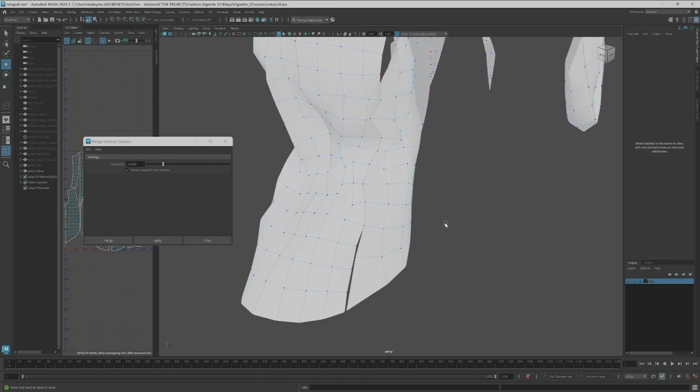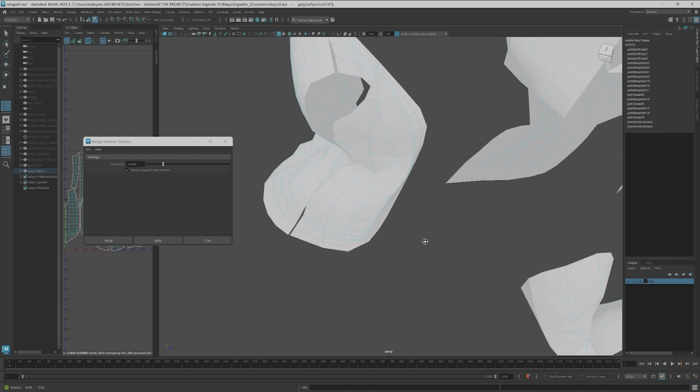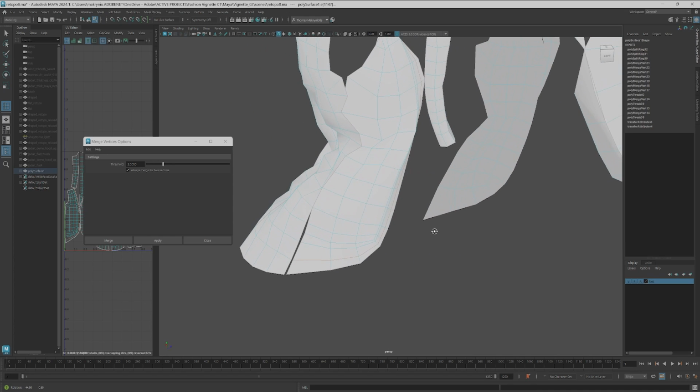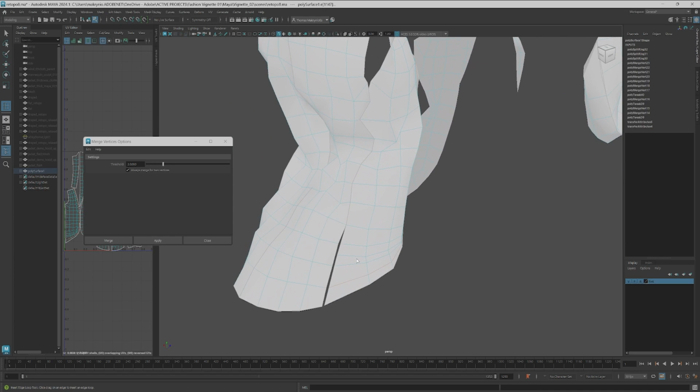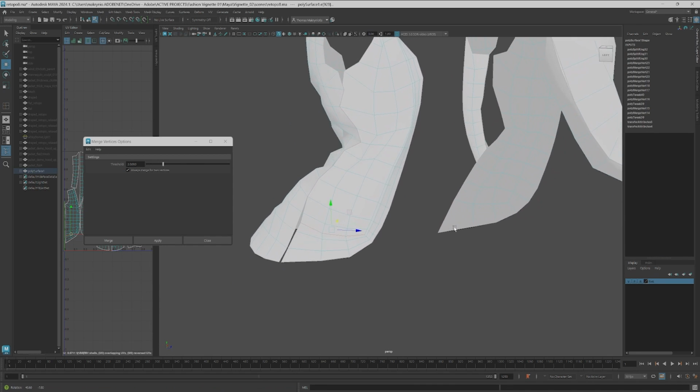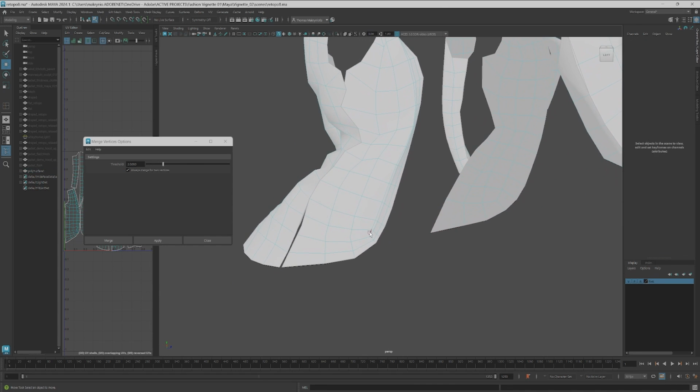The Mesh menu gives you options to select, delete, and reconstruct edges to enhance the flow of your topology. You can add extra loop edges or delete and reconstruct them to get a better flow. Try to make the topology as consistent as possible. Thankfully, we're still working at a very low resolution, so the manual work is not too much. You can also move the pieces apart if this helps you select vertices more easily.